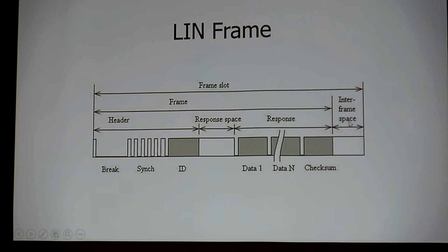These messages are all out of one processor, something like a SIM or a body control, and then he's controlling a very low-speed group: wipers, turn signals, trunk releases, whatever they choose to do with this. Most cars will have 3 buses. It's very common. The other thing is on the newer cars, you'll hardly ever see CAN B anymore.